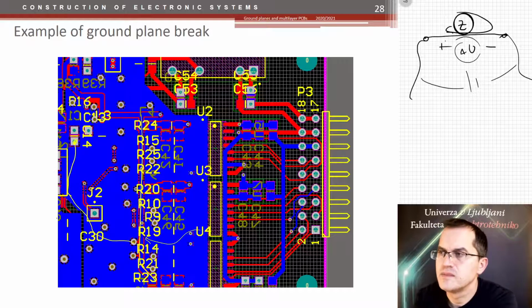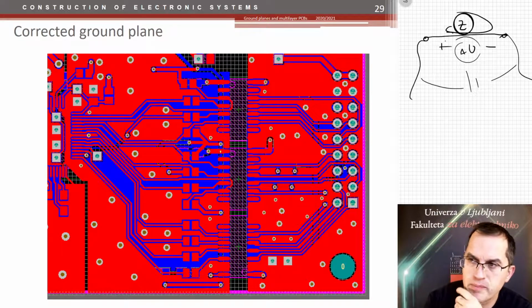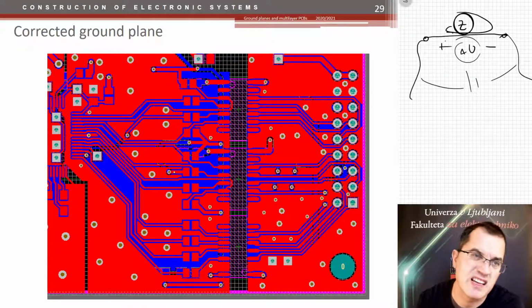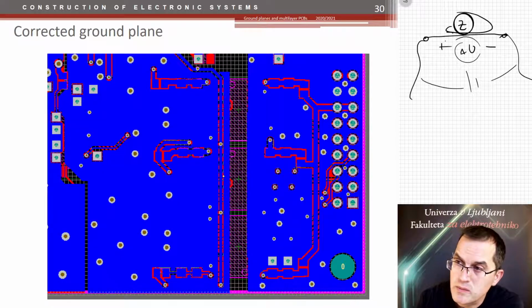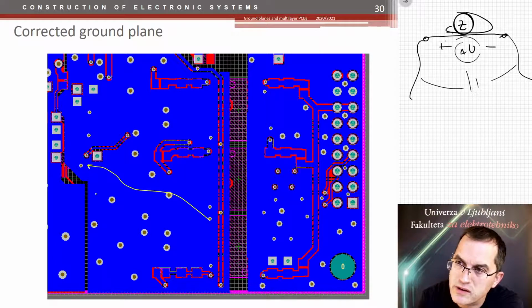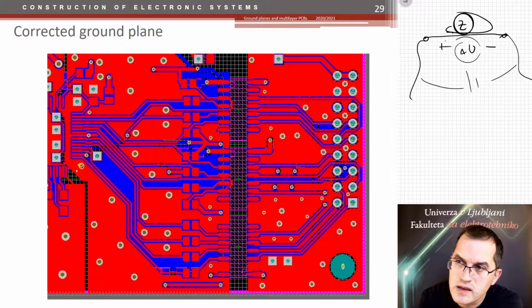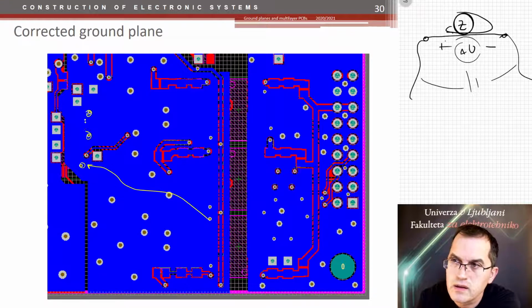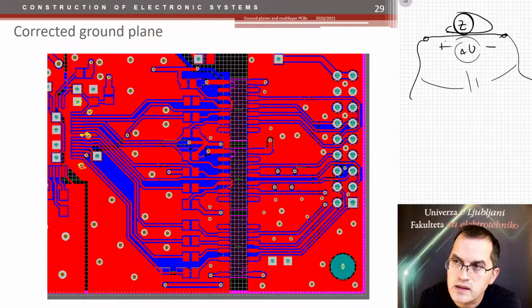So what we did was replace just a few things. We put a few extra wires, about 10 years ago or so. We also moved this track from here to the edge, so that these ground connections were on this side. Now there was a continuous ground plane to the source, and also wires here, here, here, here. All the wires that connect the ground plane to the top layer can then return back to the ground pins of this microcontroller.